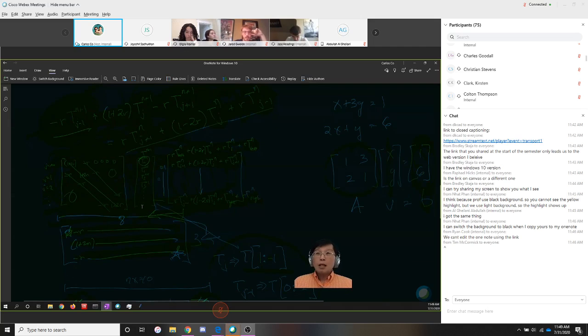And so what happens is that this is that unknown temperature. The temperature here corresponds to the last one, that would be T49, I believe. So you'll have this one, which is for T49 down here, which you don't know. Notice if you look at the equation for T49, you're going to have this negative r here, which should be multiplying the coefficient for T48 above it. So this stays one diagonal down.